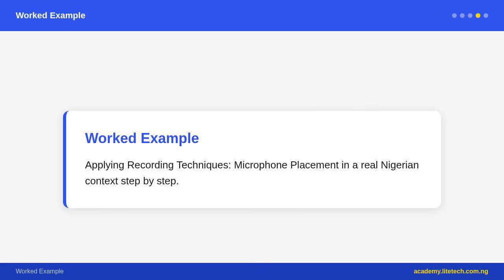Stereo recording techniques using 2 microphones create a stereo image. The XY technique places two cardioid microphones at 90 degrees to each other with their capsules as close as possible. The AB technique places two omnidirectional microphones spaced apart to capture a wide stereo image.